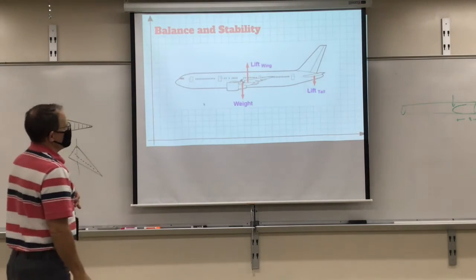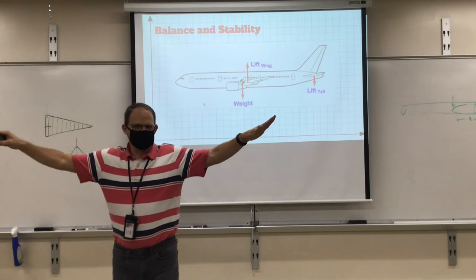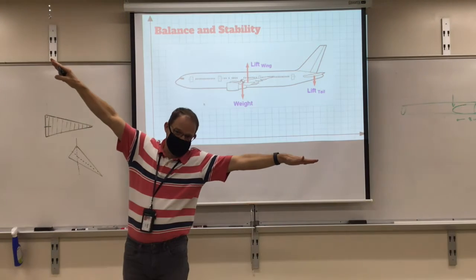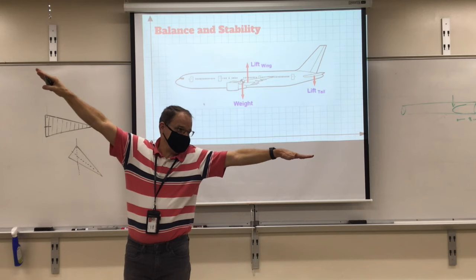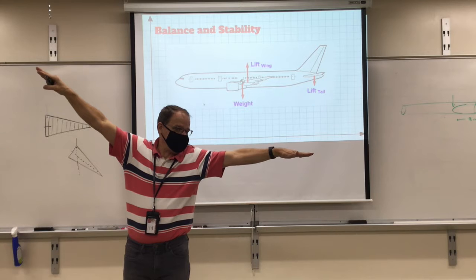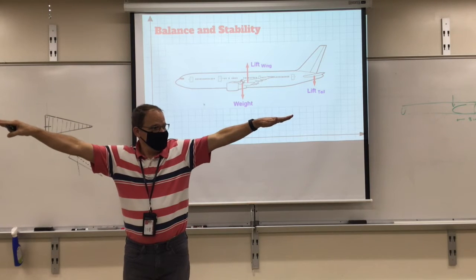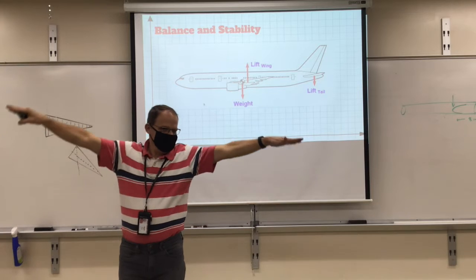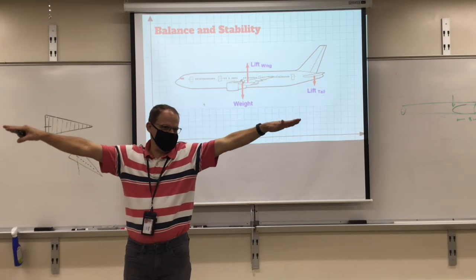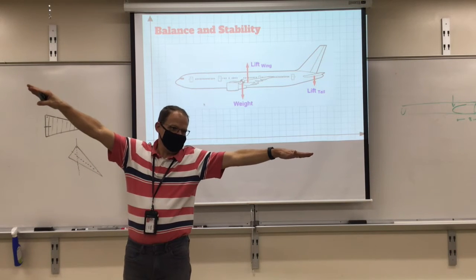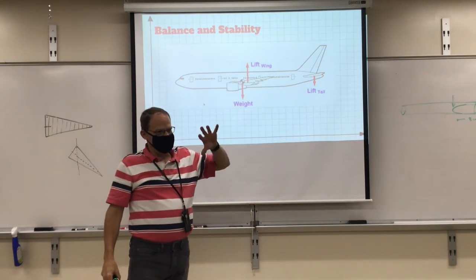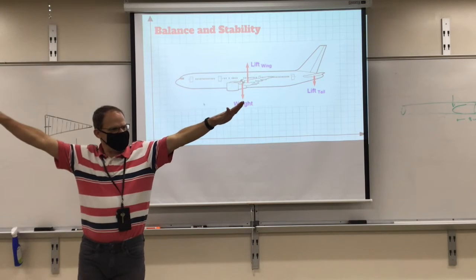We do this with airplane wings. Airplane wings have what's called dihedral. They're actually not flat. They're up a little bit. So when you bank like this, this wing, because it's now horizontal, gives you more lift than this wing. And if this wing is giving you more lift, what will happen? It'll tend to right itself. So perturbations tend to be corrected automatically by the extra lift. So when your airplane turns this way a little bit, okay, it doesn't just keep rolling. You actually have to really carefully engineer if you want it to roll, like a fighter jet. But most airplane wings are up a little bit, okay?